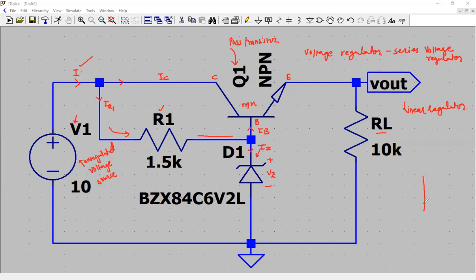Remember, you have output characteristics I versus V, and when you have a voltage in a reverse bias condition, the voltage across the Zener exceeds the Vz, the diode starts conducting a current. So that's your current here. And it is a constant voltage irrespective of the changes in the current from cathode to anode.